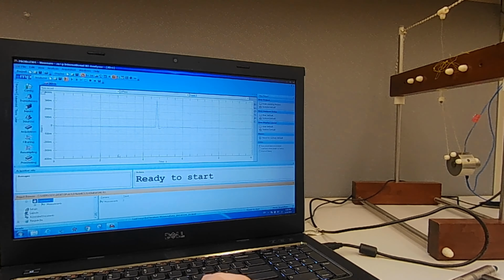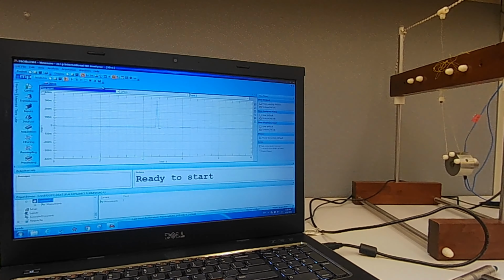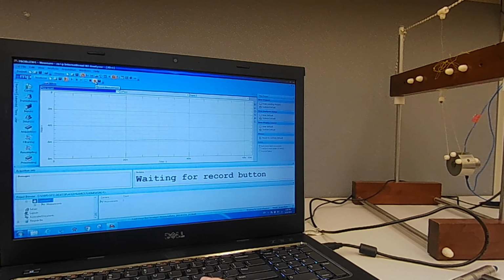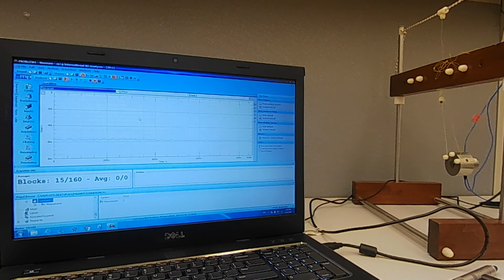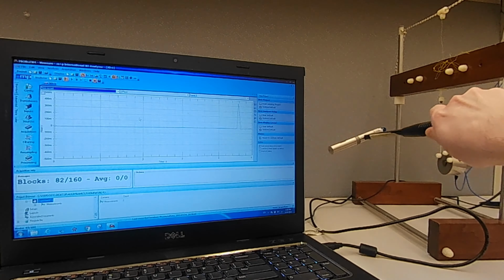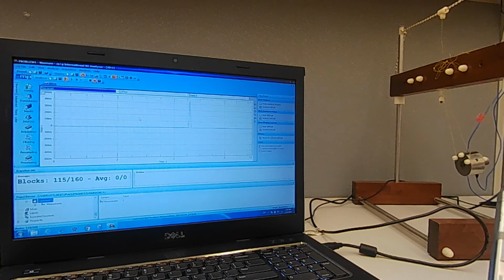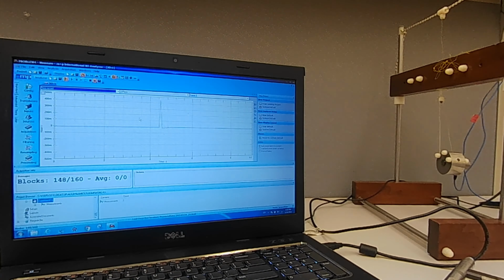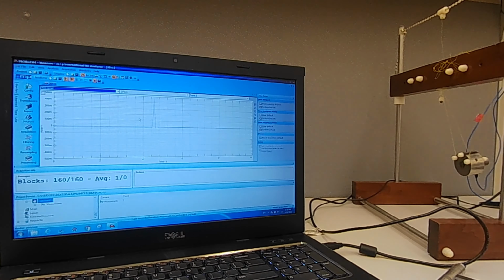And of course, the last process in this whole experiment is to do the actual experiment, and we press the record option. This is 10 seconds, so quickly we take the hammer and boom. And of course, we would have to repeat this a couple of times to get a more accurate assessment of the sensitivity value.